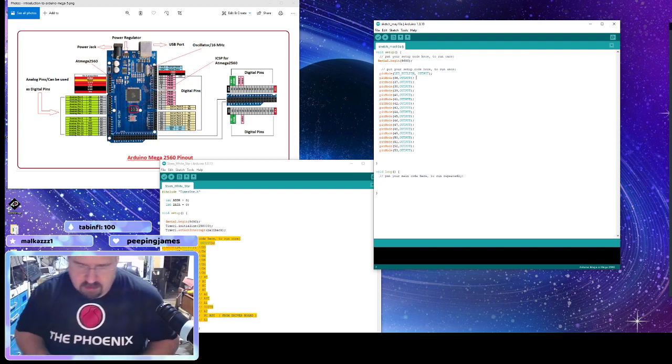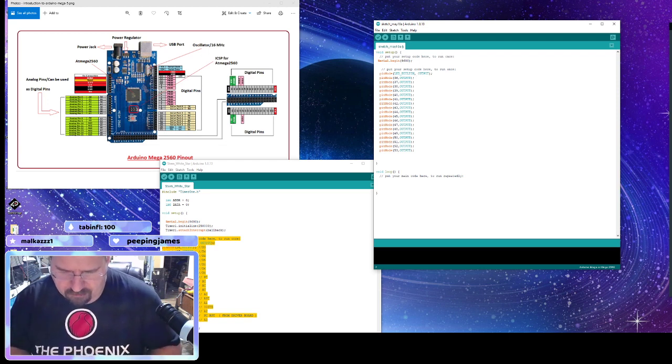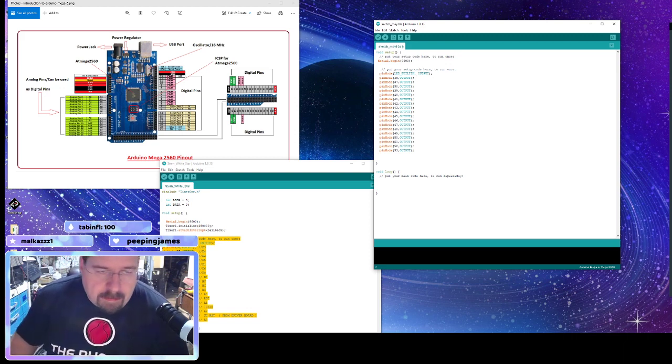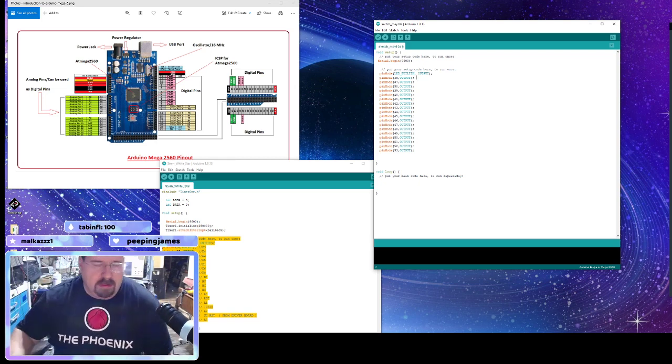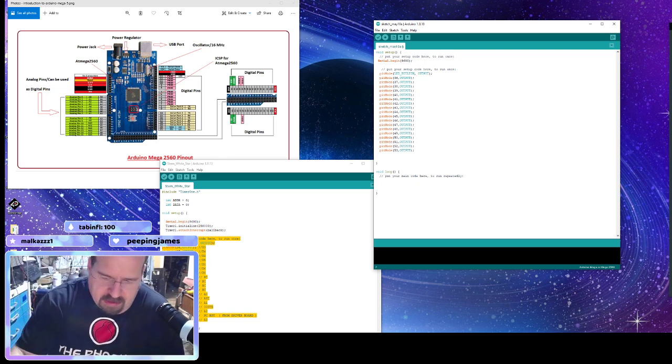Here's the screen. Alright, so we have ground and 5 volts down here. This pin is ground on here. Then the next one next to it is 5. So we can actually use the 5 volts off the Arduino. But we do need to keep the ground reference. The good thing is there's a ground pin right here. These two pins are ground. Unfortunately, that means we can't use a ribbon cable because the display's output enable is the lower pin.